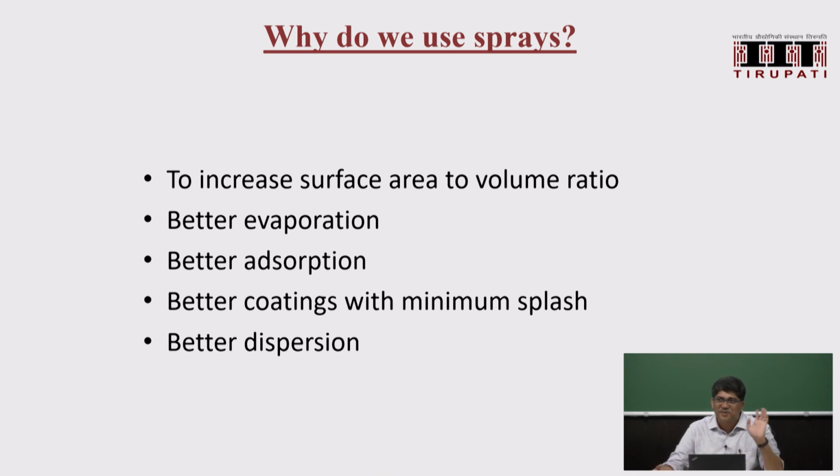Then you may ask, can I make really fine drops, say a few microns? Is it always good? There is a problem with that also. It depends on the application. You can't make really small drops, because they will not have enough momentum. If you make really small drops, the momentum will be really small because the mass is small. They lose momentum quickly and will not be able to penetrate.